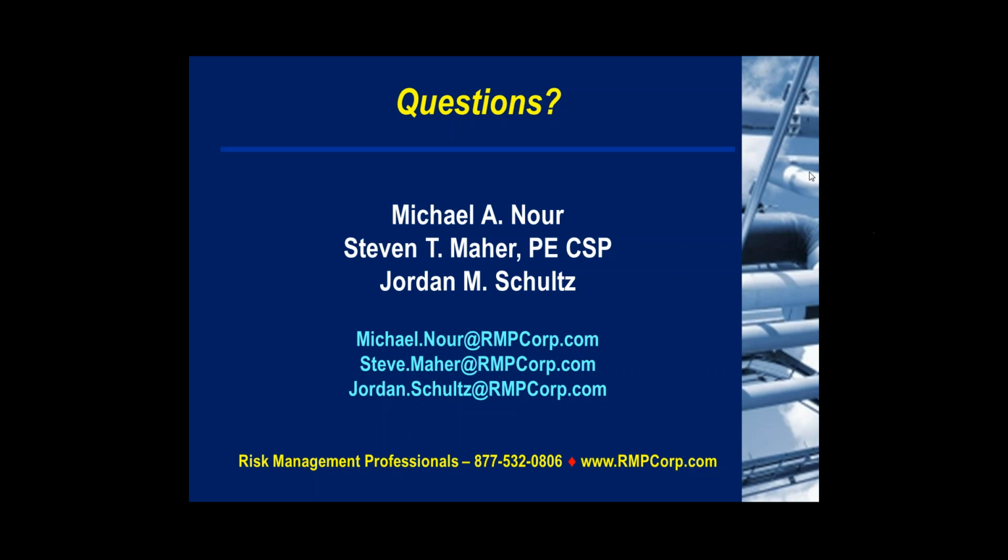You saw management of organizational change. The SPA is a safeguard protection analysis. That is a validation that safeguards are appropriately effective. A lot of that is accomplished by a good, thorough LOPA that's coupled with the HAZOP study. HCA is a hierarchy of hazard control analysis. Most of you would recognize that as part of an inherently safer systems evaluation, or at least a core part of that. These are other elements that are required.